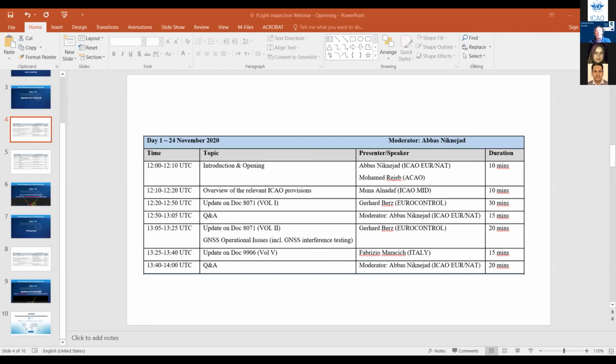Who is responsible for providing the safety oversight on the flight inspection system, given that most inspectors are experienced in CNS and not in the FIS? Yes, of course, this needs suitably trained oversight. But if you go through the Doc 8071 guidance and check every point that is in there, I think you can already become a quite educated inspector. So if the company that does your flight inspection is ready to give you good answers on all of these questions, then I think you quickly see whether they know what they're doing or not, I hope at least.